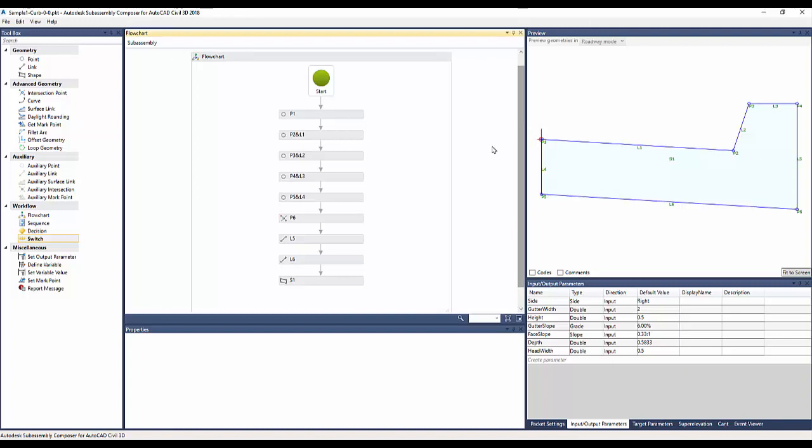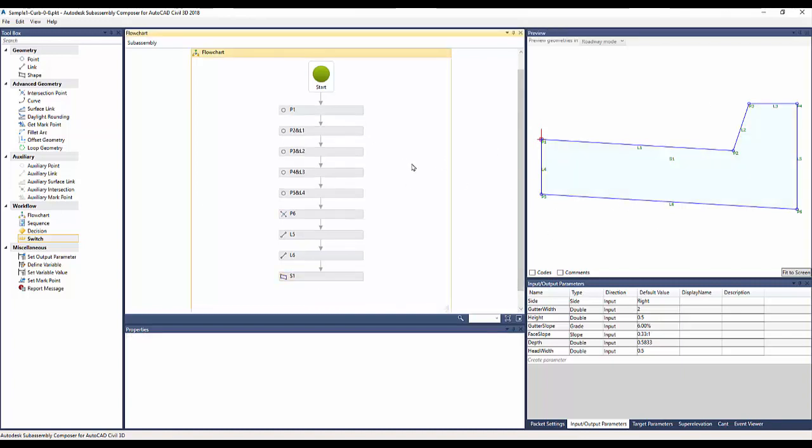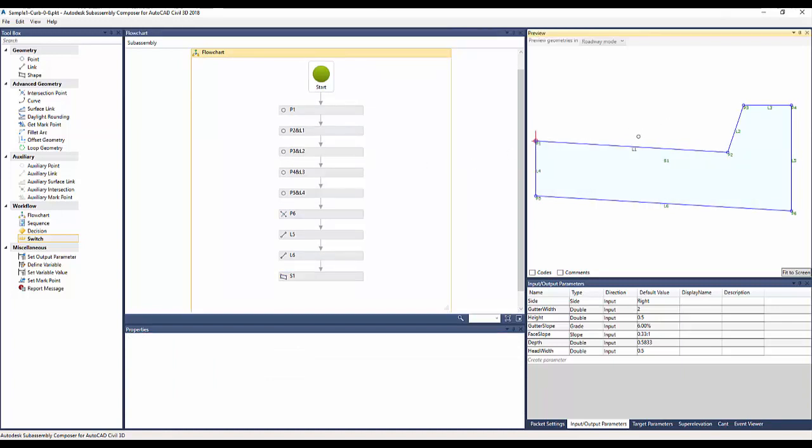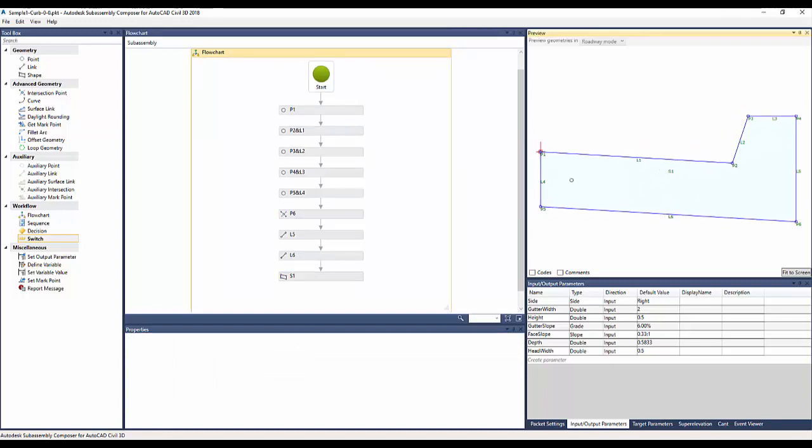It's basically we just drew a closed shape and then added a shape to the end for it to fill that in. And if we brought this inside Civil 3D, we wouldn't be able to do anything with it. So if we did want to add a really simple conditional, something that people often want out of a curb subassembly is being able to change where the insertion point would be on one of these subassemblies.